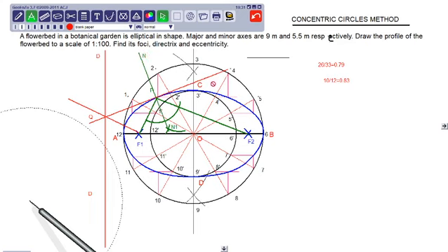Now at point P I have drawn a vertical, that is nothing but a tangent at point P. Similarly, on the line PF1, at point F1 I have drawn a vertical. These verticals and the vertical tangent at point P intersect each other at point Q. Now draw a vertical at point Q. That vertical is nothing but the directrix. This is how I have drawn the directrix.